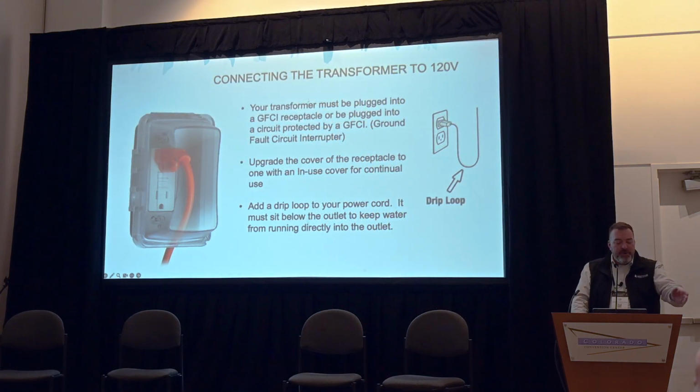Also, when connecting the transformer, you need to make sure you're using an in-use cover because it's not a temporary use. You're going to be plugged in all the time.